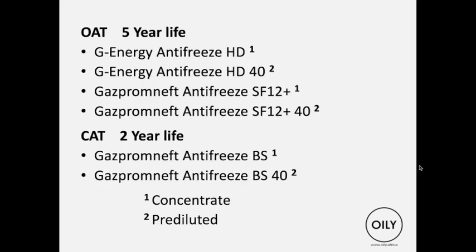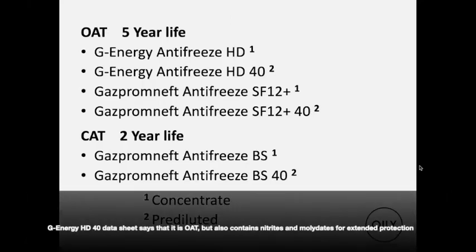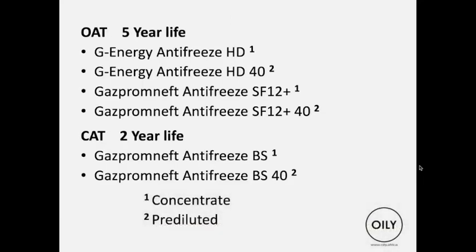Neil is pointing something out. The HD40 data sheet says it is OAT, but that it also contains nitrites and molybdates. Is this compatible with OAT? It is OATs technology. Nitrites are typically used as an additive to prevent cavitation, the liner pitting.